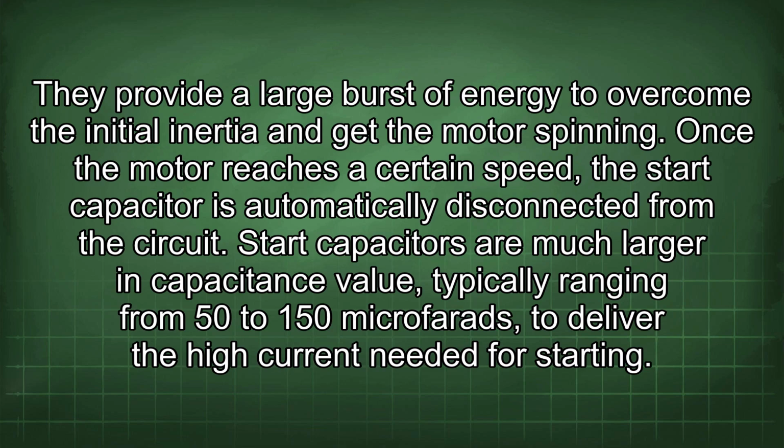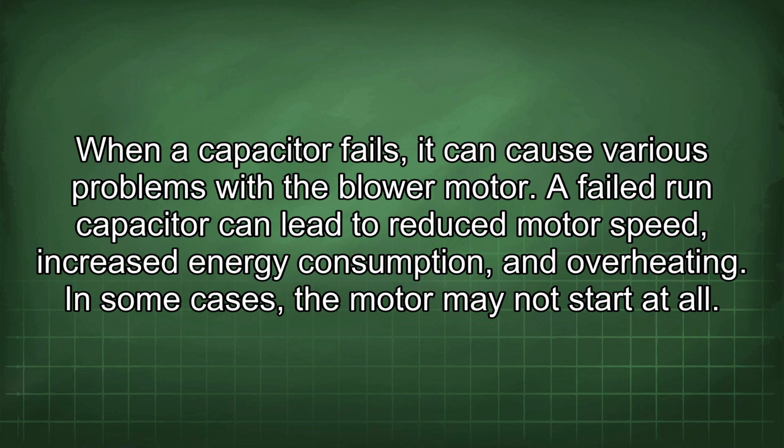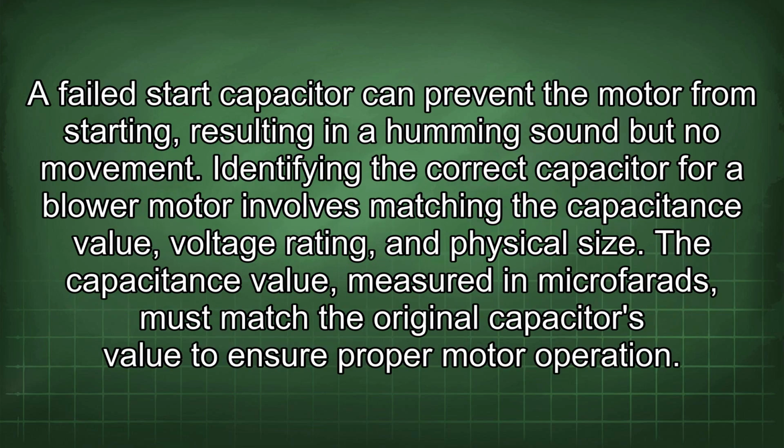When a capacitor fails, it can cause various problems with the blower motor. A failed run capacitor can lead to reduced motor speed, increased energy consumption, and overheating. In some cases, the motor may not start at all. A failed start capacitor can prevent the motor from starting, resulting in a humming sound, but no movement.